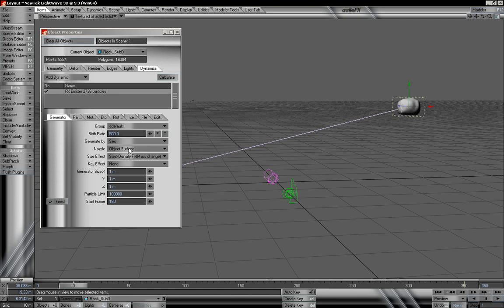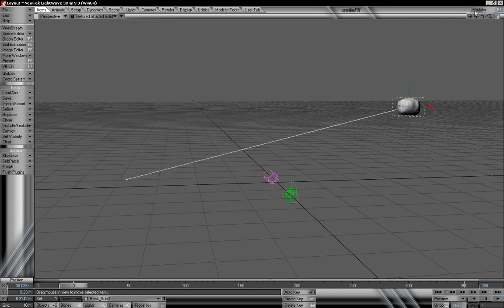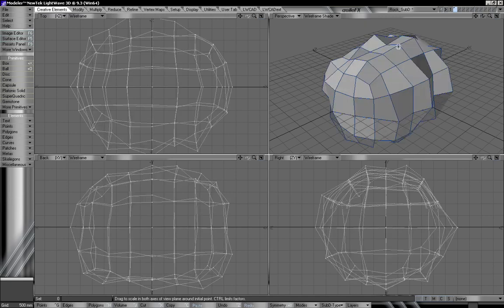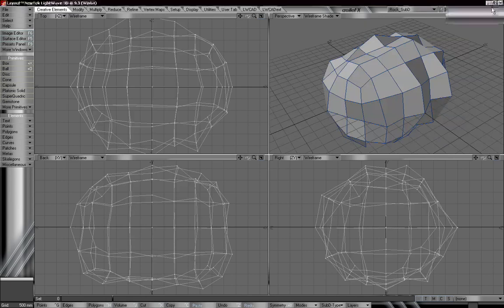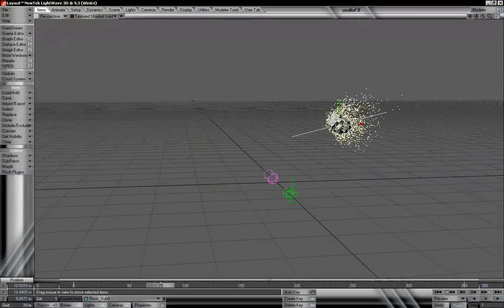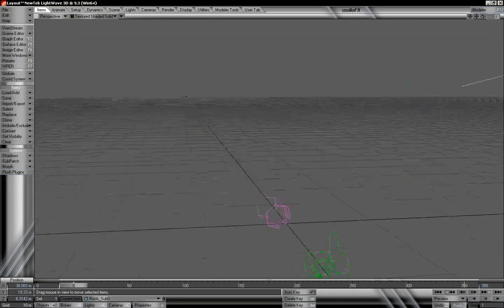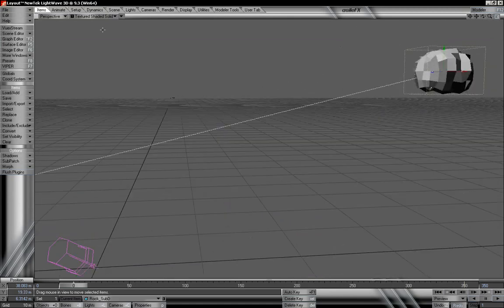And what I want to do is just reduce this and turn off our subdivisions. I'm going to turn off fixed, and we're going to go over to Modeler and just hit Tab on the keyboard to remove the sub D, and then switch to Layout. And now we can take a look at a polygon object, or a reduced polygon, because of course sub Ds are still polygons. And I'm going to switch this to our wireframe mode.